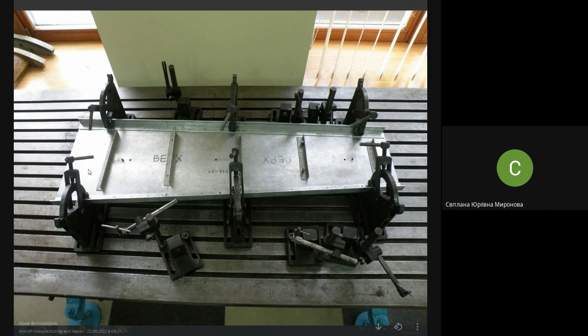On one hand, caps are located by contour. On the other hand, the web is located by CFH holes, by holes, which is another way of locating, another method. And moreover, it appears that assembly holes are also in use. Why do we call it locating in a jig by contour? Because when you assemble something, really you use a whole heap of methods.